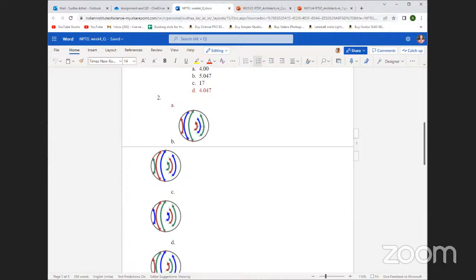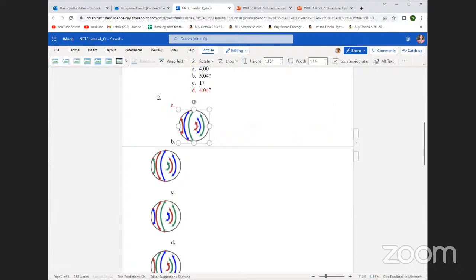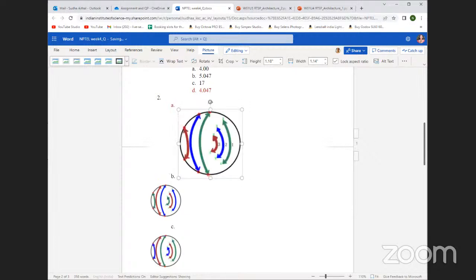The one that we usually consider is the farthest from the zero. This is our origin, and from here the farthest one is what we take as my pole. So this pole is the farthest from the origin, and it is combined with the zero which is nearest to 0.